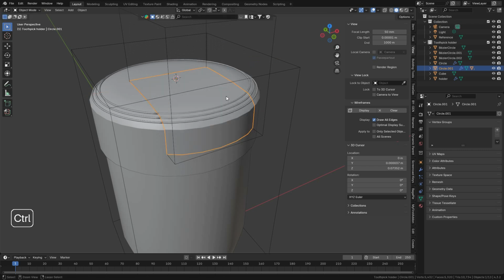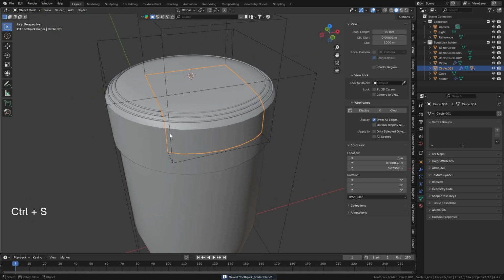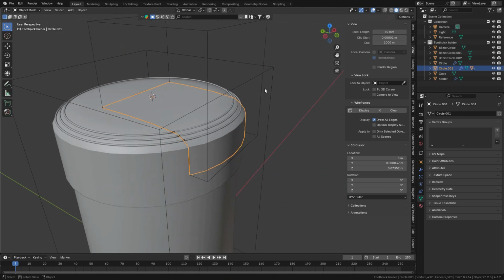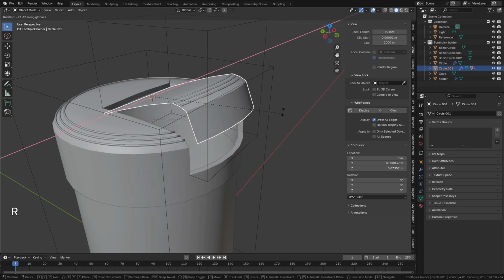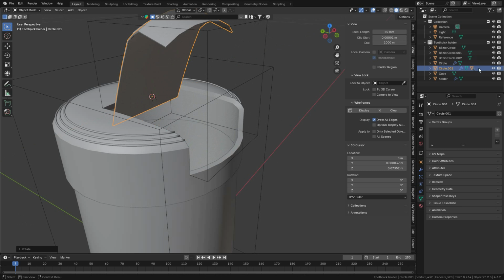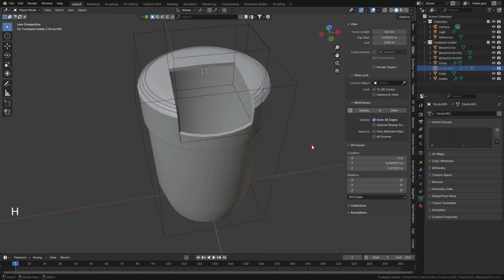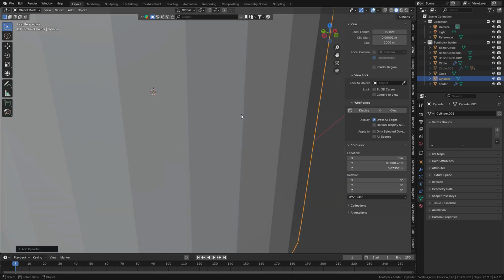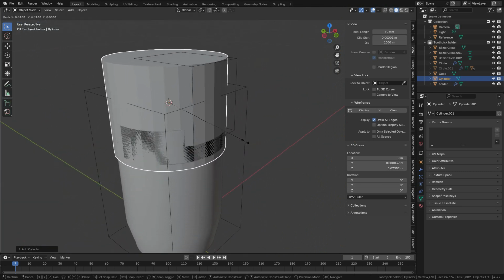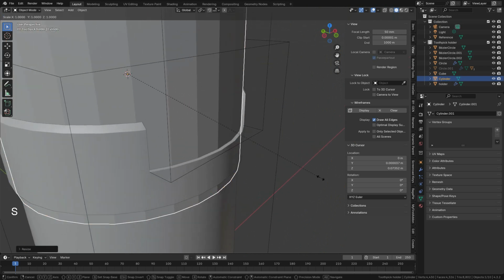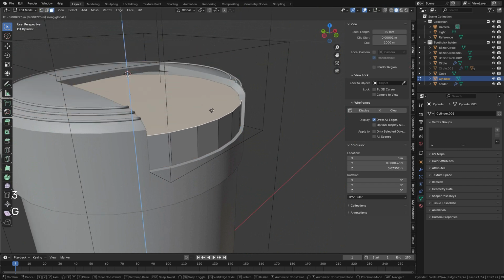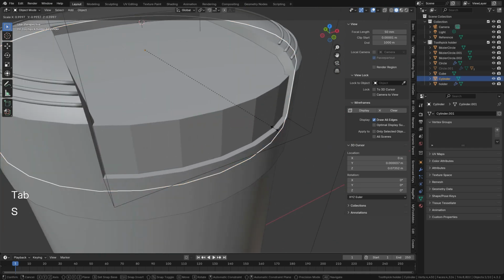So now that this is working nicely, you can go ahead and save your project if not. Now what you want to do is work on the inner parts where the toothpicks have little holes where they come out of. So to do that, in order to view it, you have to rotate this maybe and make it open. Another thing you can do is right click this, select hierarchy and press H to hide it. Now you're going to work on that part. So I have to add a new cylinder, mesh cylinder. Scale this down to about here. Scale Z. Then you're just putting it in the correct dimensions. Go to edit mode, select this face, bring it down. I think about this much should be okay.